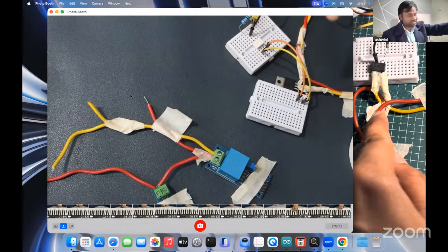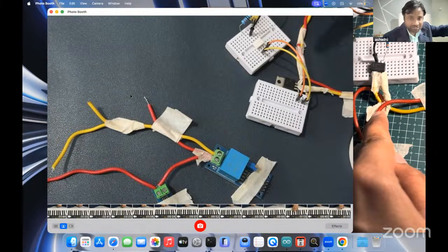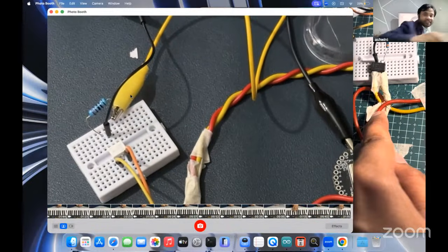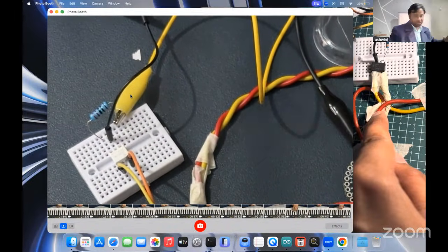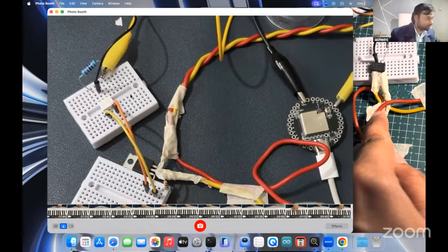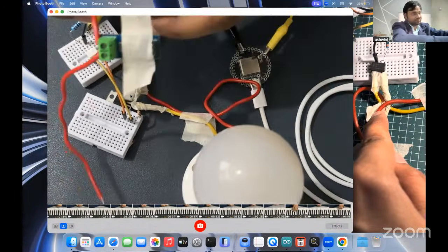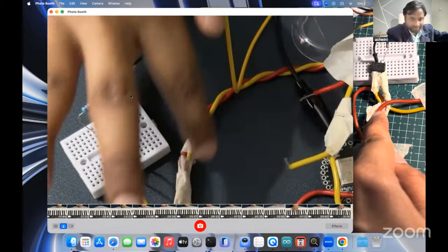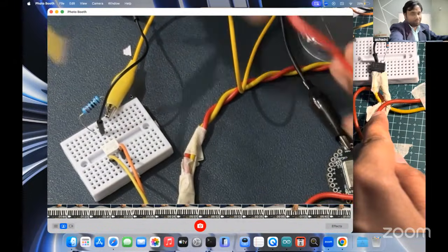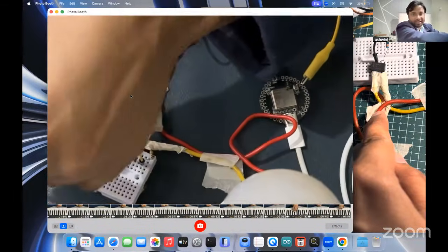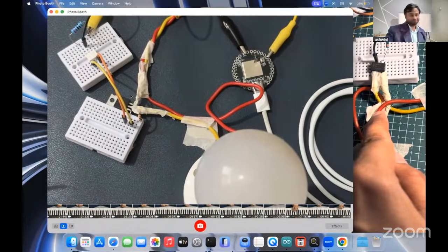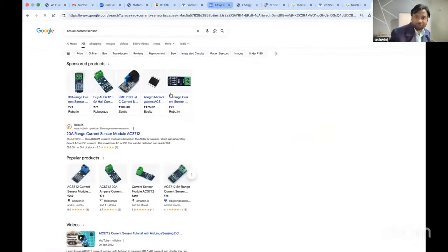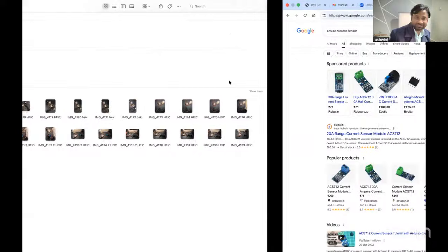Right now this is connected in this configuration, so I am not touching it because it is the AC line. I don't want to cause a short circuit, because we need a careful connection. But I have told you that this connection will go to the opto triac, like we have done here, and these two wires go to the plug. After that it will start giving readings, and then you need to upload this code, and it will give you the total billing and all those things.